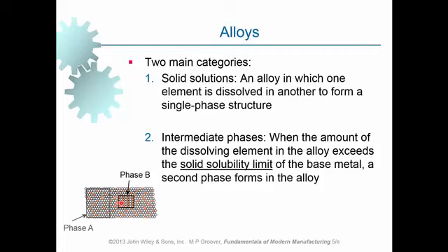When crystalline structure is different, what is meant by this? Say, for example, if you are having BCC crystalline structure in this region, and we are having FCC crystalline structure in this region, then the number of slip planes and slip systems will be different in different regions. And we know from the Materials and Manufacturing 1 unit that certain properties of the metallic materials are a function of the number of slip systems present in the given crystal structure.